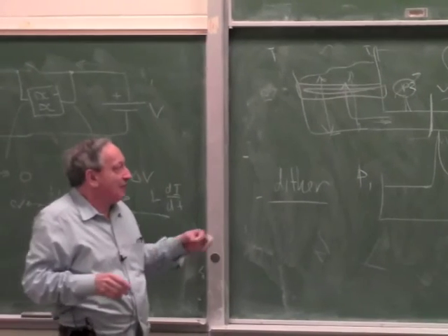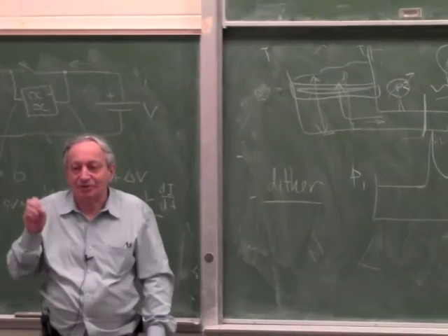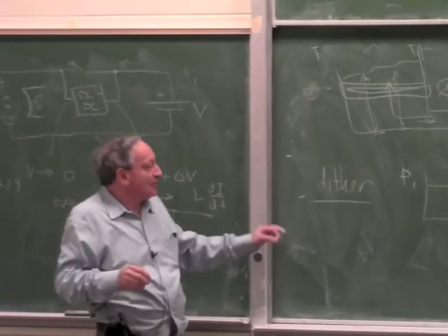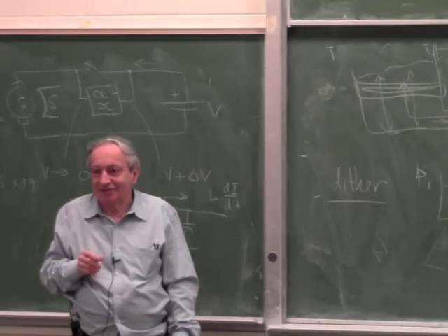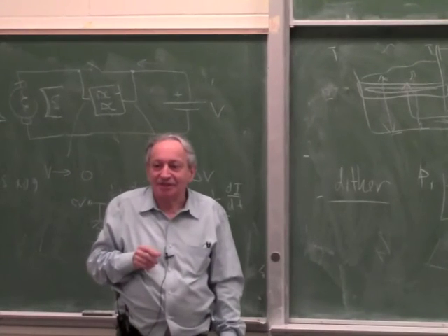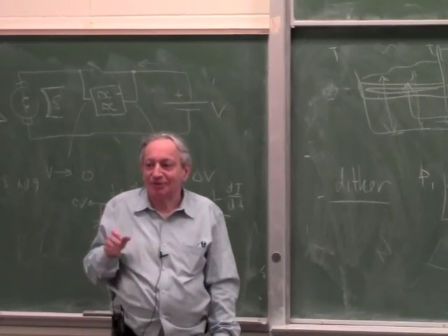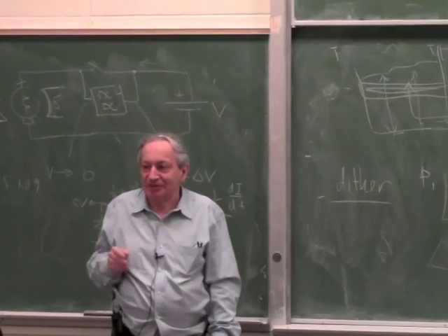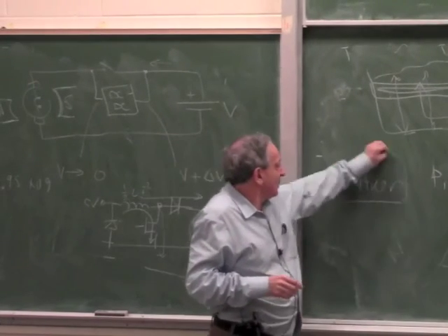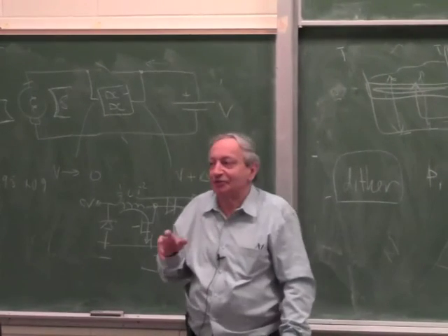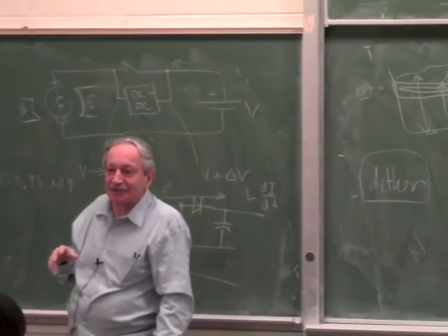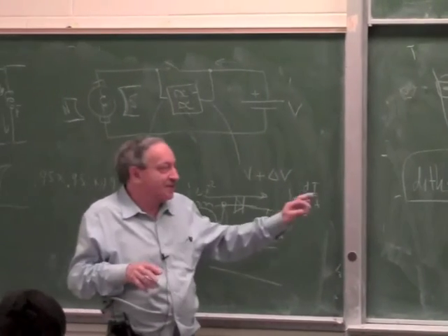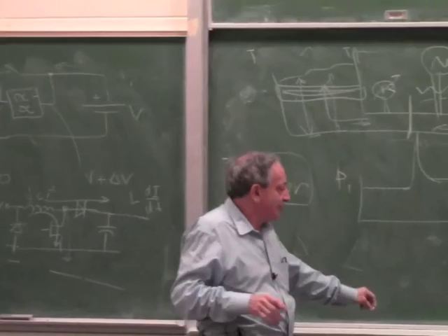So if you have some mechanical systems, you also introduce dither. You want to take out any static friction. But in hydraulic systems, it's almost impossible to do without it if you want a very high performance servo. So this is the only time where you'll see something equivalent to AC in a hydraulic servo. Anyway, that's just an example that a servo doesn't have to be electrical.